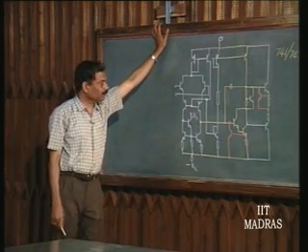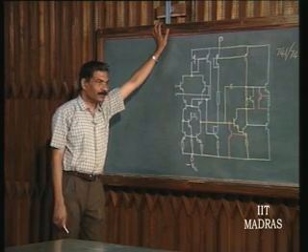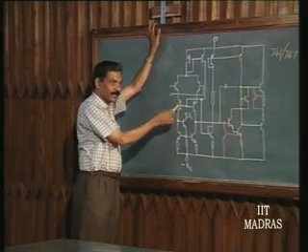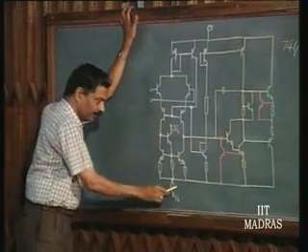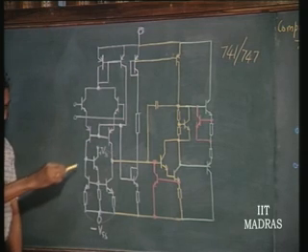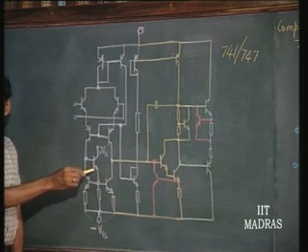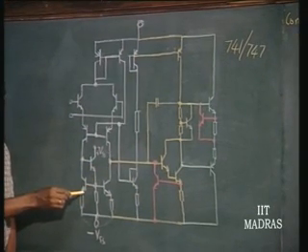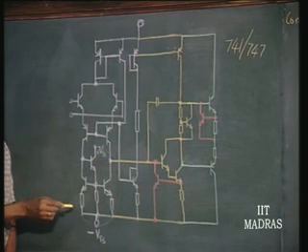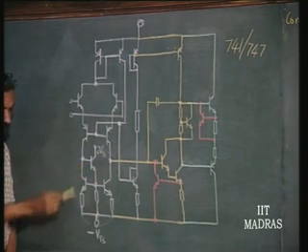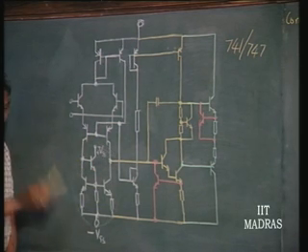okay, in white color. Obviously, in the input stage we have decided to use NPN current sink as the active load, okay, to the input stage. So, you can see this active load here, okay. This is the same block that I had discussed with the current amplifier put there, so that the current reflection here is exact, okay. So, this is nothing but the current mirror active load using NPN structures.